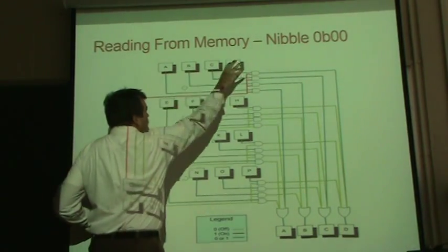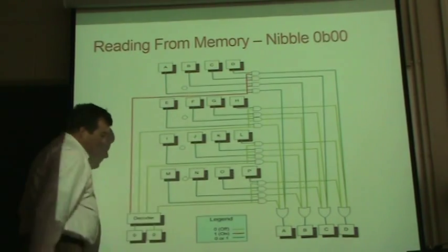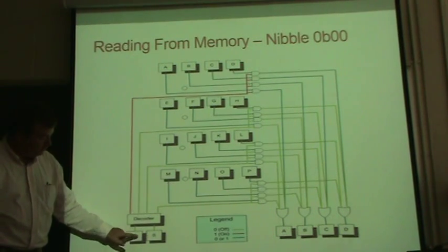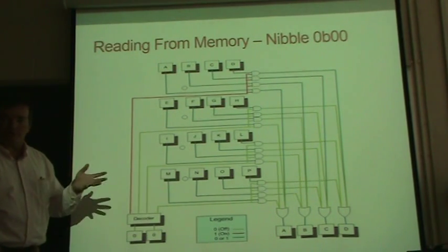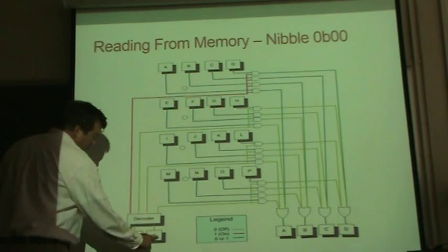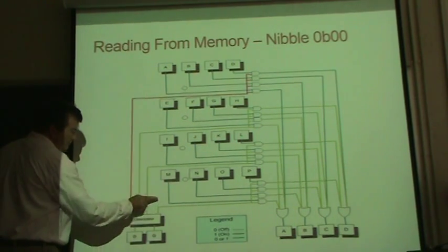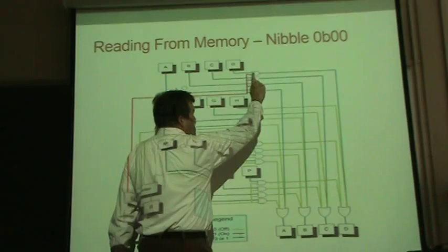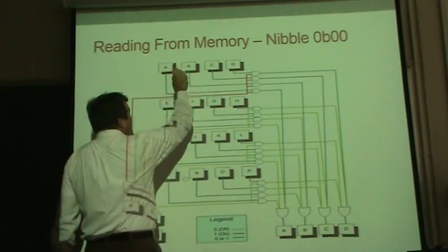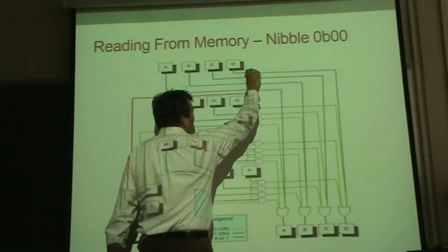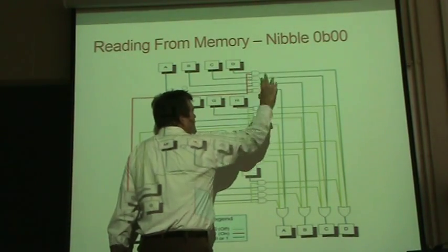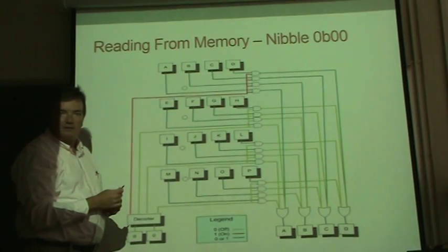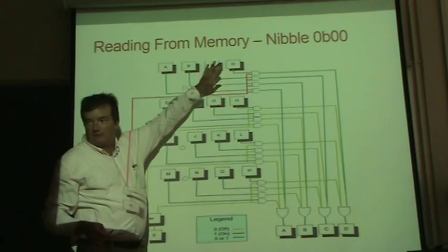And so here's the 0 set, the 1 set, the 2 set, and the 3 set. And once again, we have a decoder. So now we can pick which of the 4 sets we're interested in. So if I put 0, 0 here, this line is on and these 3 are off. This line being on turns on all of these AND gates. And the values of these 4 bits get ANDed with this line that's on. So the values coming down here are what? Whatever these are, right?